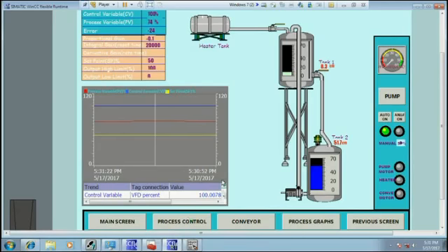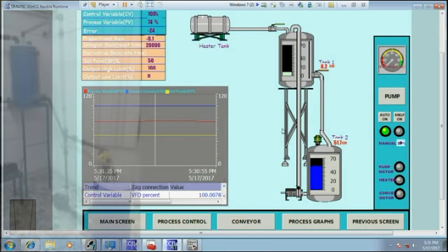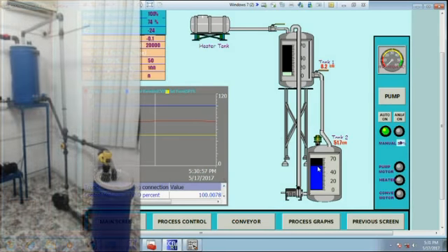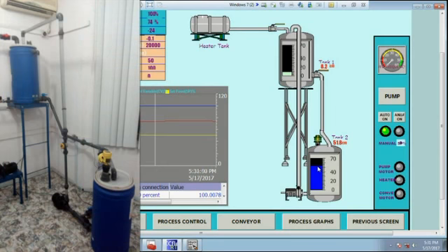So in my liquid level system, I have 2 tanks, and the tank 2 level is our main target. That's what we are trying to control. So now how this works is I have liquid from tank 1 pouring into tank 2, and as you can see, I have a level meter on tank 2, and there's a pump down here that drains the liquid in tank 2 back to tank 1. Now up here I have a valve, a discharge valve, that causes a disturbance in the system so that the liquid level in tank 2 varies above and below the set point.